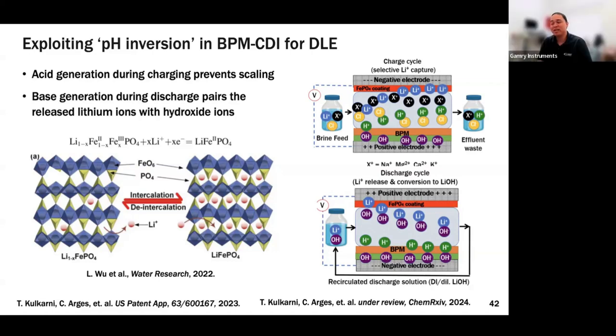Definitely, I felt it. Okay, we have one question from a person who asked, how do you actually make the in situ measurements of solution pH? Were you pulling a sample downstream? We have a device with conductivity and pH probes right at the effluent, and that's where we're measuring the pH. We're not making any local measurement within the process chamber, but it's more of a bulk measurement in the effluent stream. Got it.